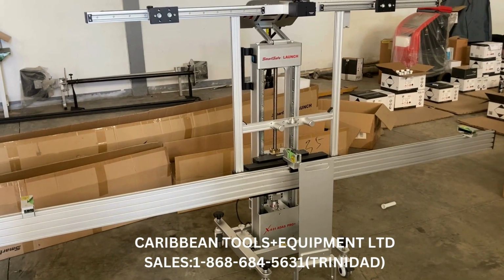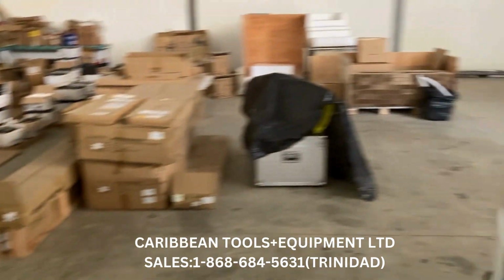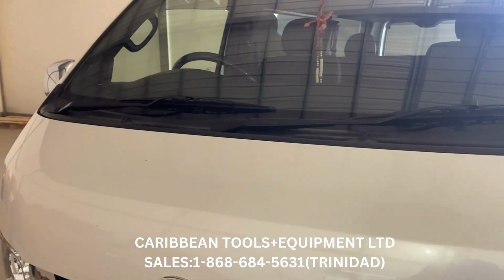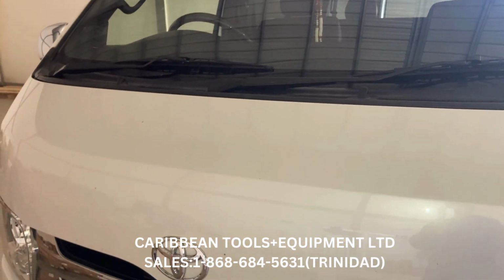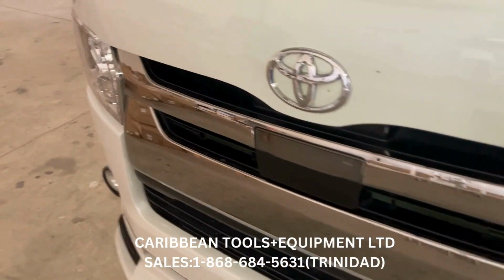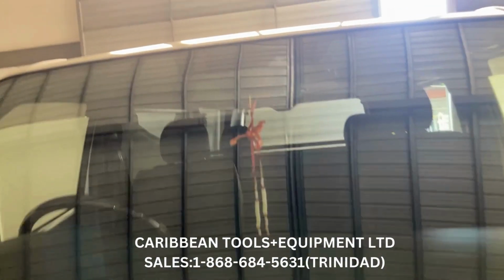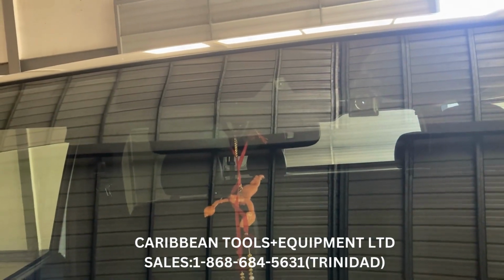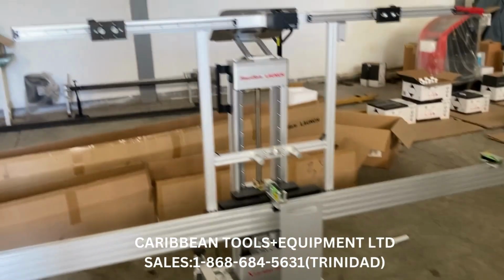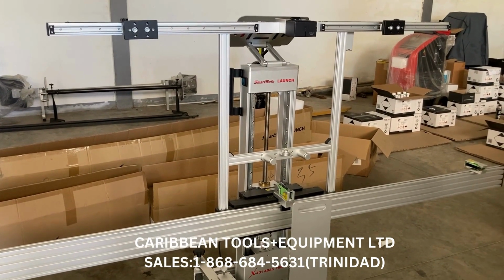So now we will do a demonstration on how to use an ADAS calibration frame. Right, so we have the ADAS calibration frame positioned and we have the vehicle. And how do we know this vehicle carries ADAS? On the grille, there's a front collision warning sensor, and on the windscreen, there's a camera. So we will use this frame to calibrate the ADAS system on this vehicle.